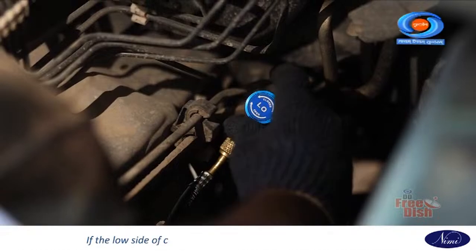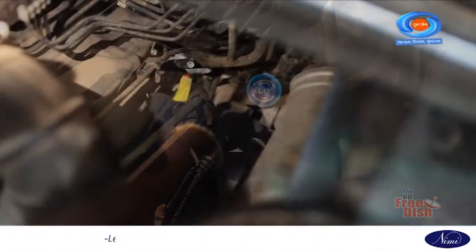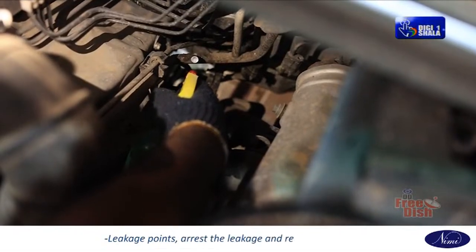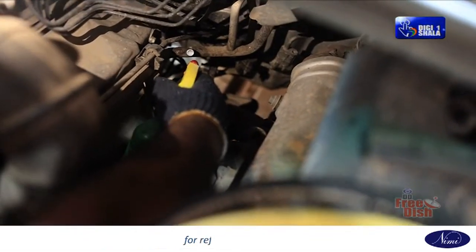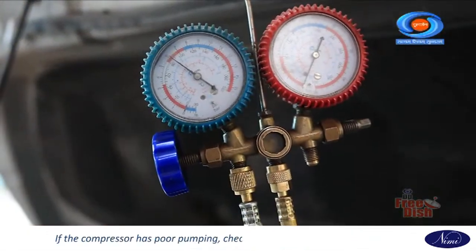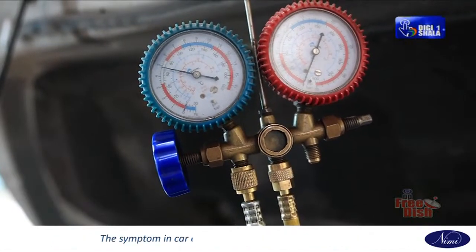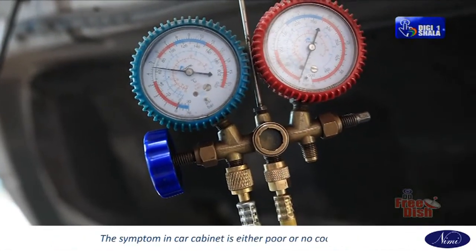If the low side of the car AC system is lower than normal, check for leakage points, arrest the leakage and reprocess the system for refrigerant charging. If the compressor has poor pumping, check the performance of the compressor. The system in the car cabin has either poor or no cooling effect.